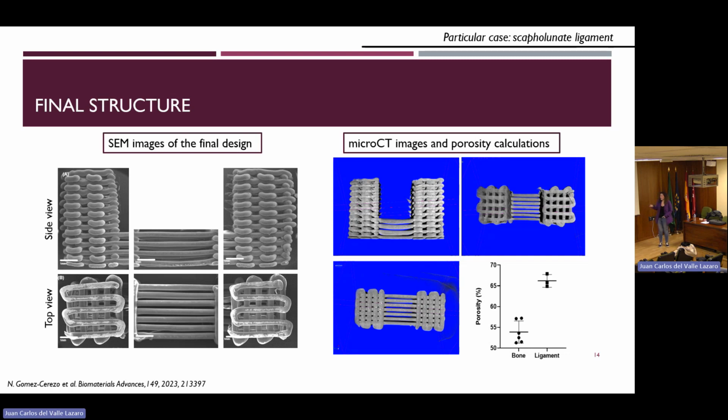In this case, I think it was a good approach and it was based on the simulation maybe. We also got this nozzle because we did some trials printing with a smaller nozzle. This one is 0.4 and the other was 0.2. And again, the mechanical properties weren't as good.